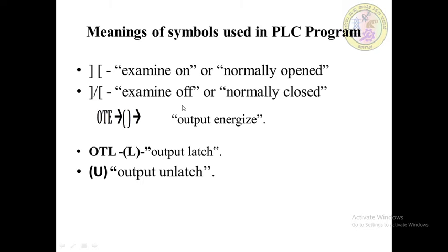Whereas with output energize, the instruction sets that specific bit when the rung is continuously true. Under normal operating conditions, if the bit corresponds to an output device, the output device will be energized when the rung goes true. For example, output bit is 0, so the slot 3 will operate.